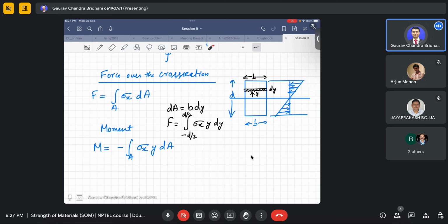Okay, yeah. So this way we do actually. So what we do, because we don't know how to convert this dA into simpler things, is how it has been done in literature. You take a very small strip and you know the width remains b. So okay, I am missing, I think, something here. I should write a b instead of y. Sorry, yeah, it should be b, not y, dy, because I have replaced dA with b into dy.